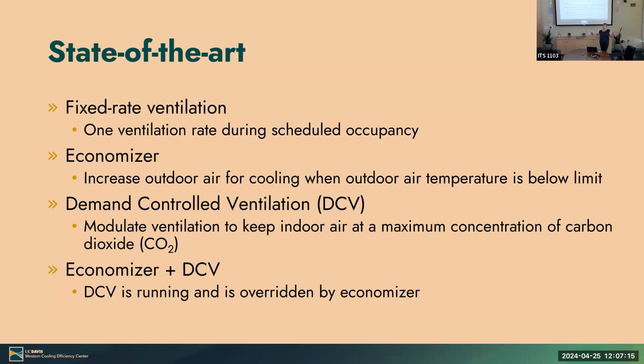Classrooms are very densely occupied, and so they have large cooling loads. And so we could need cooling. It might be 10 degrees Celsius outside, and we still need cooling because we essentially have a room full of little heaters, right? And so that's what an economizer does.